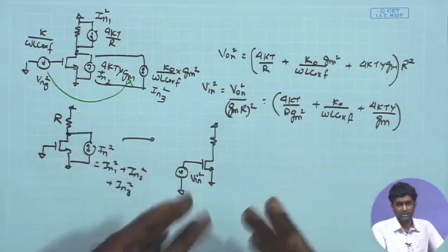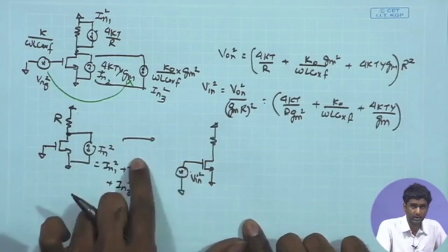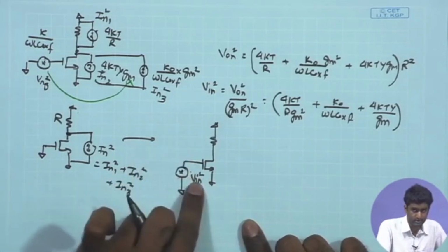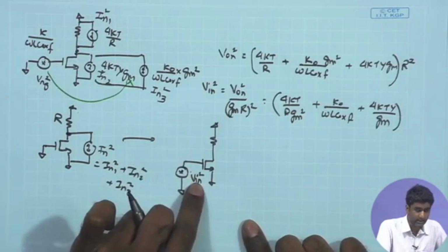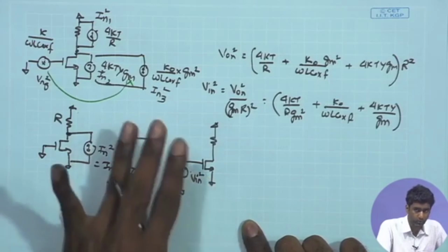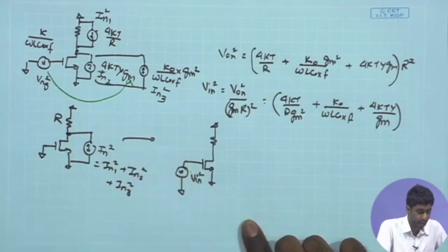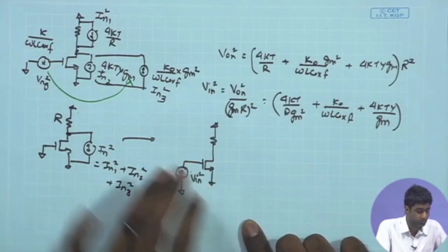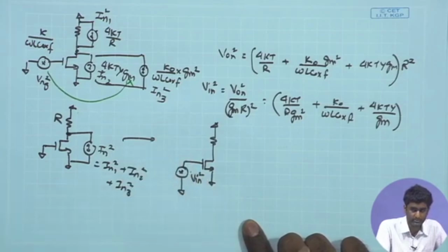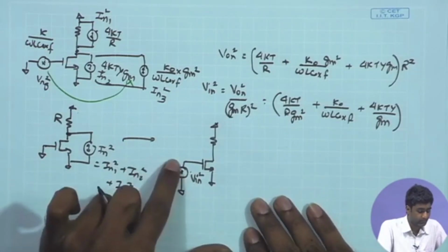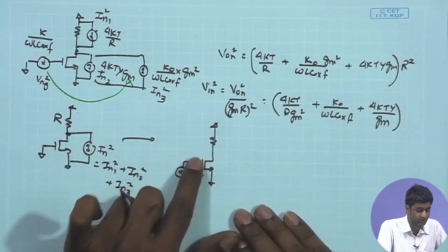For example, if I want 7-bit precision or 7-bit accuracy in the recorded data, and the data coming over here is 1 millivolt peak to peak, I would like to make sure that the RMS value of the noise that you have at the input point is lower than 1% of that 1 millivolt. So, this should be within 10 microvolt peak to peak. So, the RMS value should be within 10 microvolt approximately to ensure 7-bit precision for the overall amplification.